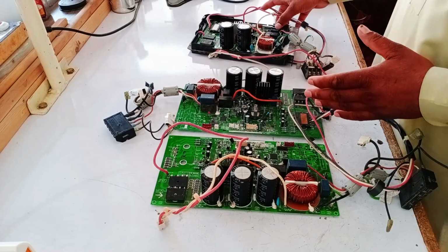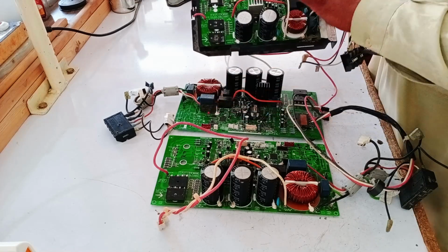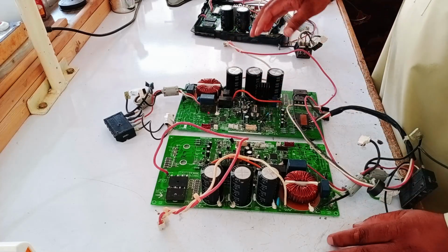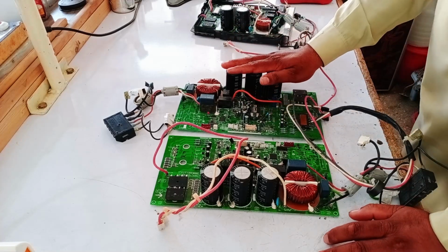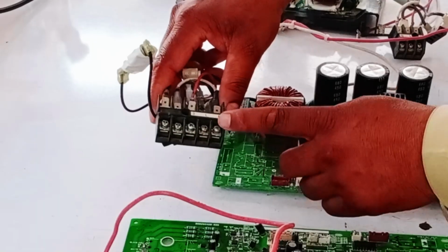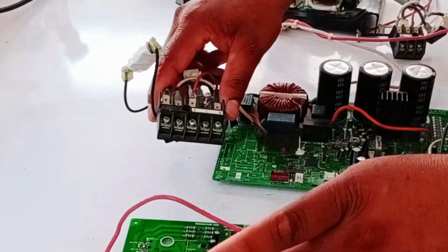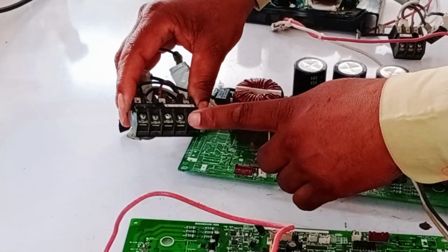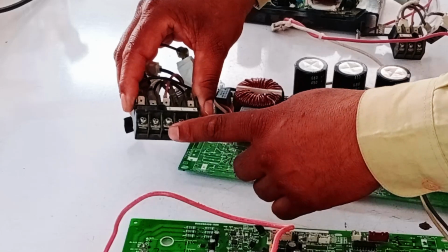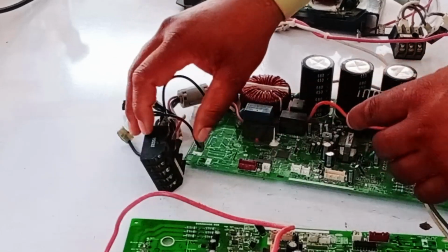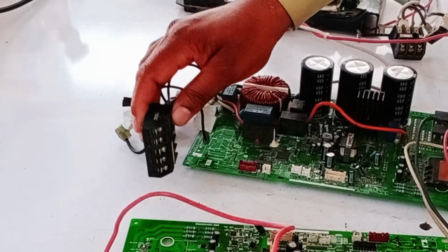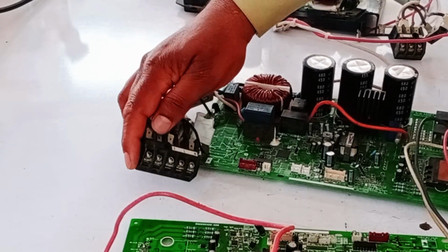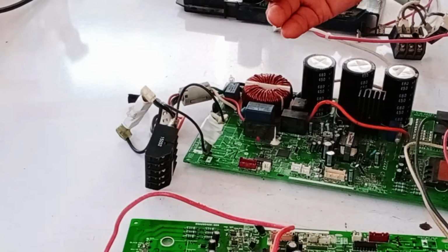Now take a look at the 1-ton unit. In this type of unit, electricity flows from the indoor unit to the outdoor unit, so the indoor unit needs to be checked more carefully. But in this case, the situation is different. Here, the supply first goes to the outdoor unit and then to the indoor unit. Therefore, it is necessary to check the wires running from the outdoor unit to the indoor unit. Make sure there are no loose connections or sparks. Often, during fluctuations, wires can get burned. That's why it's important to check their continuity and serial communication to ensure they are functioning properly.